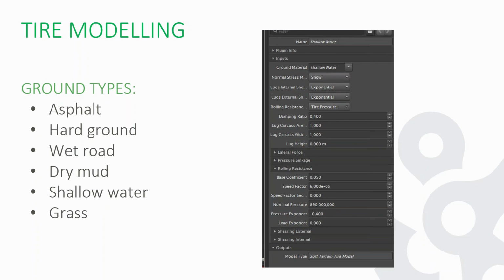So you remember that you saw me earlier flip the vehicle in the video. That was caused by me taking the turn too quickly, and the tire actually slid sidewise on the asphalt. So that's not a behavior that's easy to reproduce using just basic contact physics, but with tire model it takes into account all the forces and all the deformation, so the vehicle actually slid to the side.